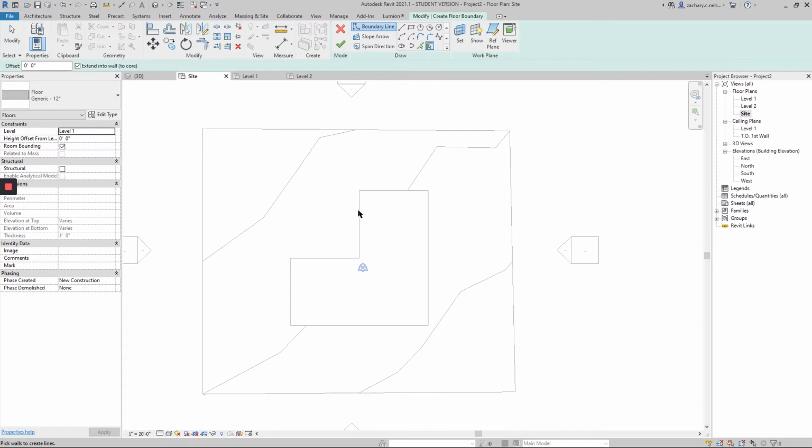And now since I already have this building pad here, rather than drawing lines on top of it, which might be a bit tedious, I can use this pick lines, which is delineated by this arrow that sits over the green line here. You'll see it highlights lines that I mouse over, and that'll just draw the lines for me. So I'll just click, click, click, click, click, and click. And now I have that L-shaped outline already, and I can just press check.